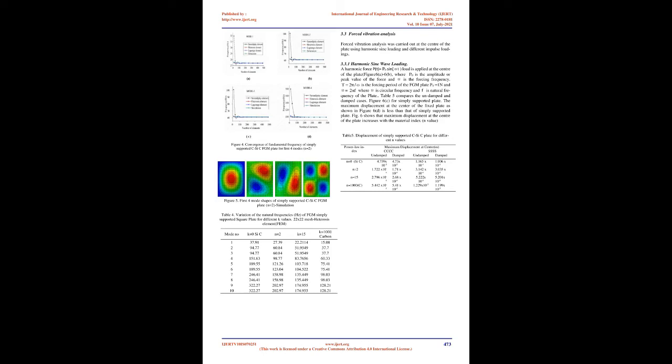2.5 Formulation of dynamic problems. The stiffness matrix is validated by bending problems and the mass matrix is validated through vibration problems. In order to validate the formulation of the mass matrix, one has to solve a free vibration problem by incorporating the validated elastic stiffness matrix. The standard governing equation in matrix form for the deflection problem is (13). 3. Results and discussion.